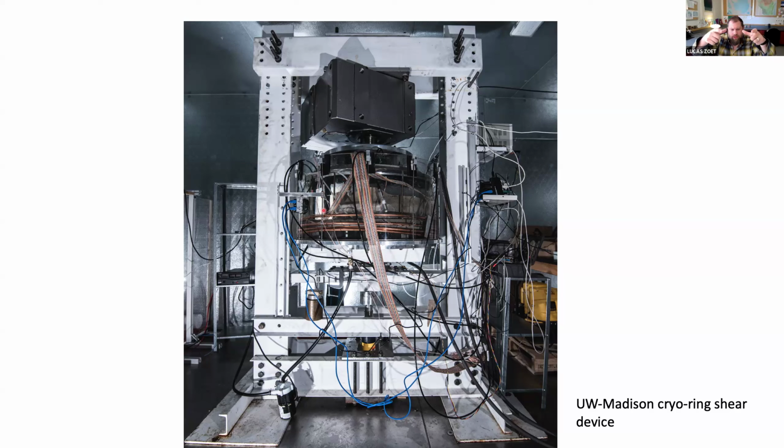And you take a disc of ice and you place it atop some bed material. So in this case, the bed material is till, right? A soft till. But you can put hard beds in there. You can put whatever you want. And then the top of the ice ring is gripped by a set of platens that spins the ice ring over the bed at a prescribed rate. And this big thing you see up here is a gearbox that's got a 2 million to 1 gear reduction ratio that allows us to generate the massive torques we need to maintain a constant sliding speed on the system.